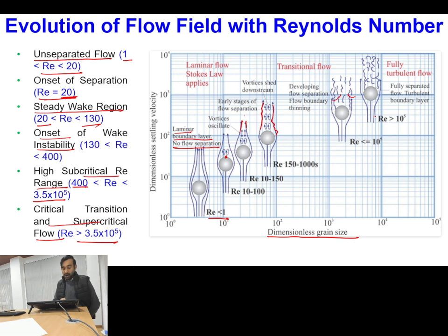So why are these two separated? There are certain reasons. What we can see is that in the majority of cases, flow behind a cylinder or a sphere has formation of oscillating vortex structures, if you see animations of experiments or numerical simulations. At Reynolds number of 400, these vortex structures start shedding from the sphere.